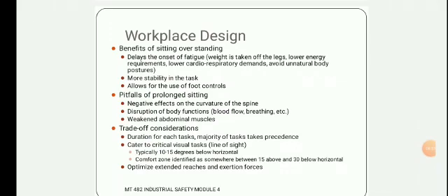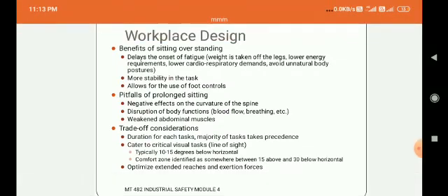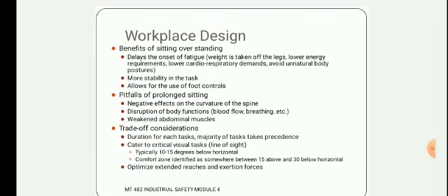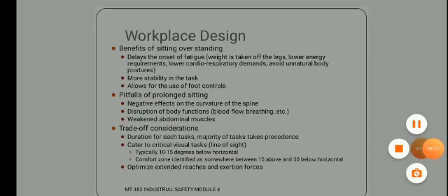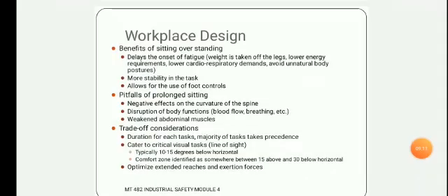Then comfort zone identified as somewhere between 15 above and 30 below horizontal. Okay, this is the comfort zone of our eye, 15 degrees above and 30 degrees below the horizontal line. This is the comfort zone. We should maintain that. Then optimize extended reaches and exertion forces.